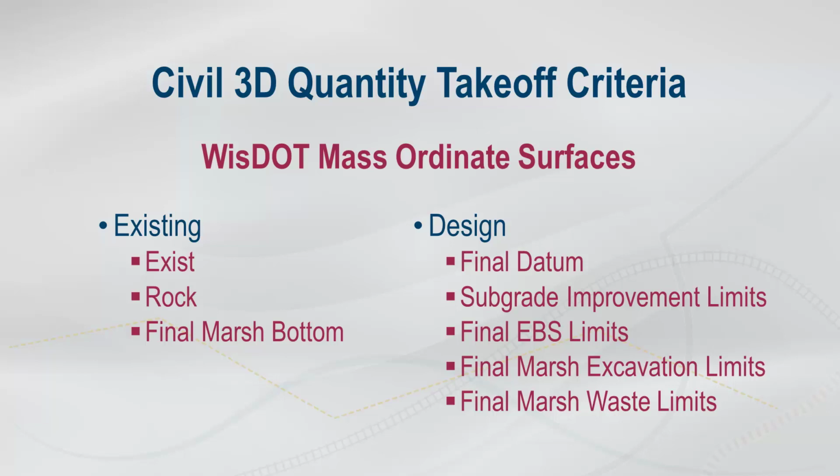This is the surface below the pavement structure, and then from the subgrade shoulder point follows the top surface of the proposed cross-section. We have a lot of information on how to develop this on our Civil 3D knowledge base, and you can go there to learn more about that. Kind of related to that is rock excavation. This would be incorporated mainly into the datum surface. If you have rock excavation, you can have steeper side slopes, and this would be built into your datum surface outside the subgrade shoulder points.